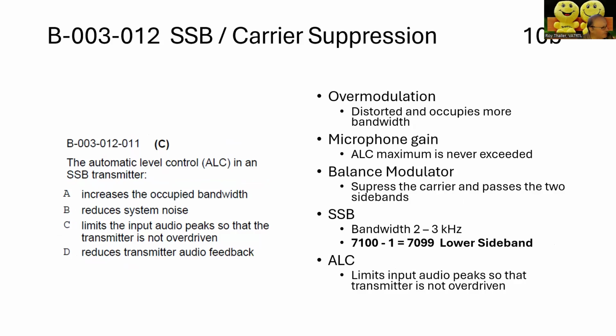The automatic level control, ALC, in a single sideband transmitter, C, limits the input audio peaks so that the transmitter is not overdriven.